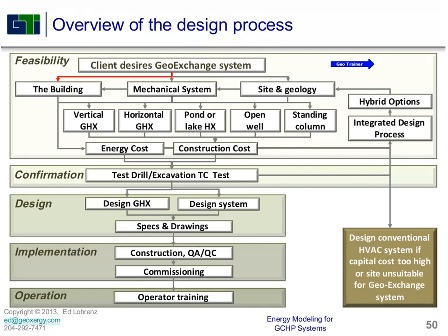Then, a design charrette is a very good place to start this process. Remember one building that we looked at where the electrical engineer presented what the cost of putting in high efficiency lighting in the building was. It was going to cost about $1.25 a square foot, about $500,000 on the building that we were looking at. They were running at about 2.5 watts a square foot